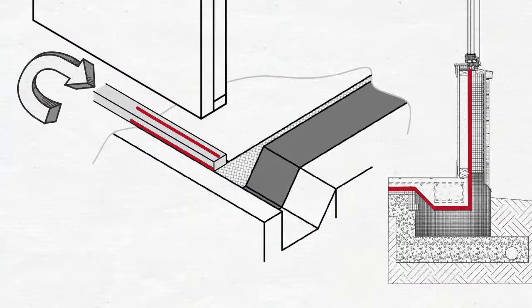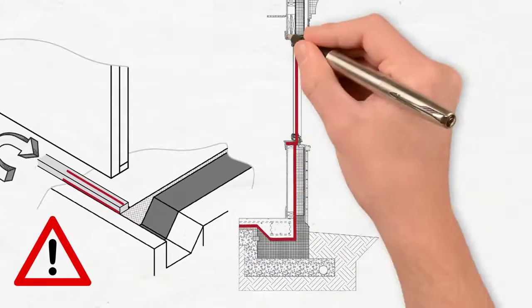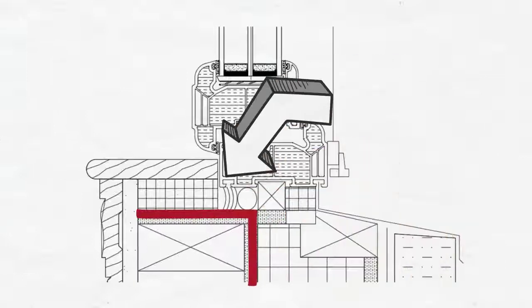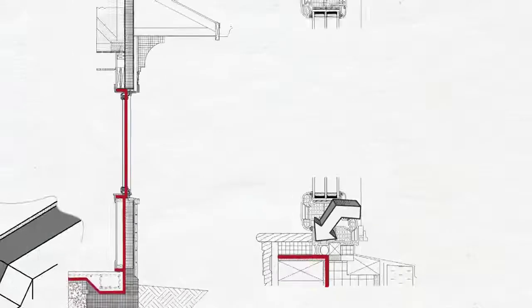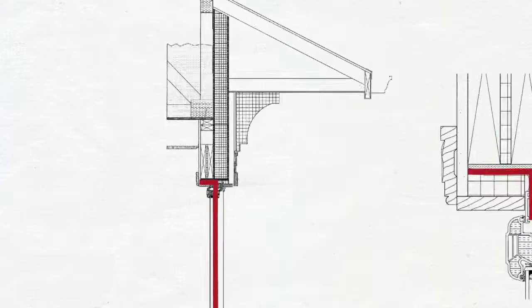All sealants need to be applied continuous with no voids or thin areas. After that, we put a sealant between the window opening and the wall. The window uses sealant which was installed during production in the factory. The same happens on all sides of the window, continuously to the top. We arrive at the top of the wall.